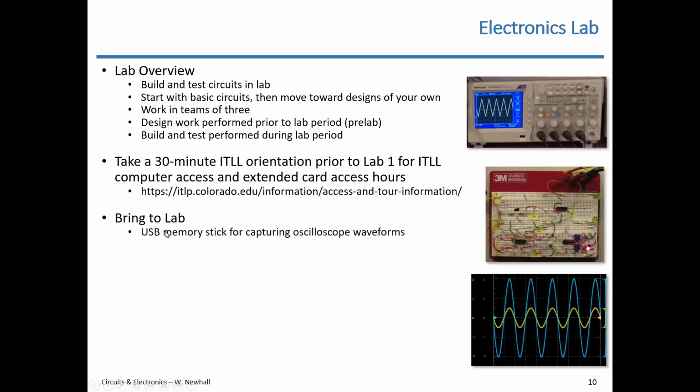So in lab, you're going to be capturing data. The point of the lab is to build a circuit, show it meets the requirements, capture data to show it does that, capture some images of your circuit. So bring a USB memory stick for capturing oscilloscope waveforms. Don't just take a picture of the screen, because a lot of times that doesn't work out. We tried that. So bring a memory stick. You can do a screen capture from the oscilloscope. But do bring a phone camera to take photos of your circuits and take photos of your measurement setup. So that will be part of the material that you insert into your lab report.